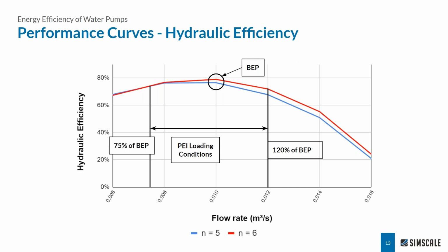To reiterate on how you're actually modeling this energy efficiency index, we're looking at that best efficiency point for each design and looking at a wide range of operating conditions to understand the head generated and the horsepower requirement of the pump impeller motor to transmit into the pump impeller, looking at all those conditions to generate the energy efficiency index.